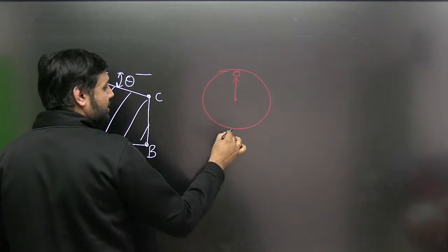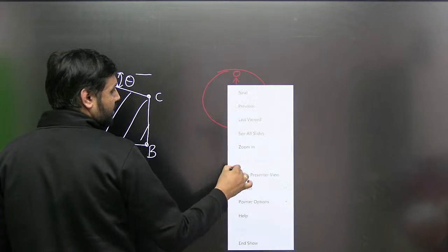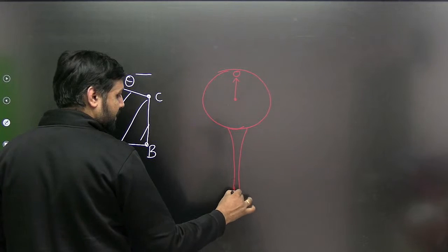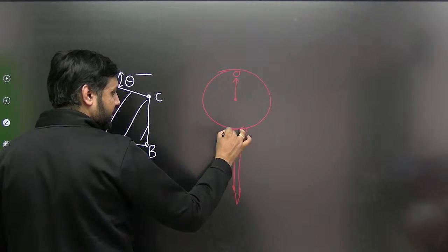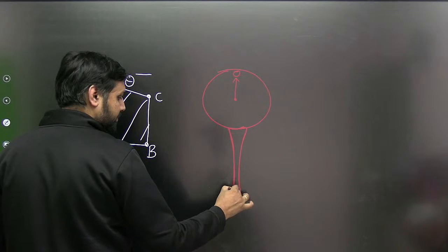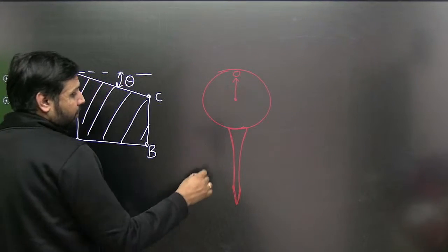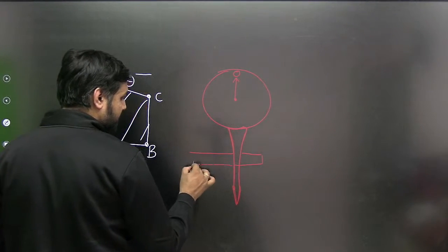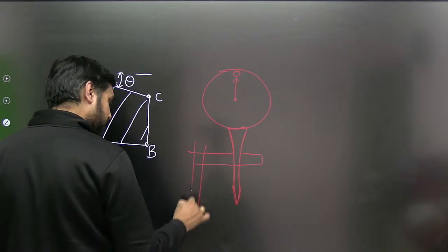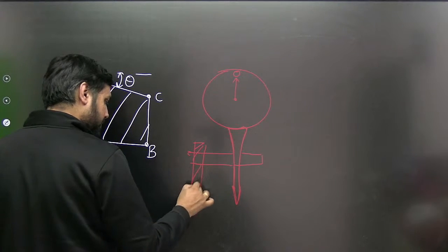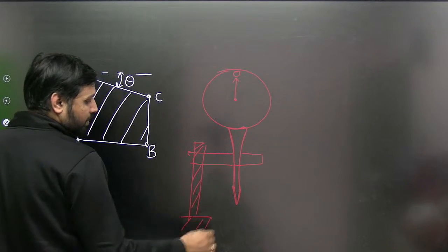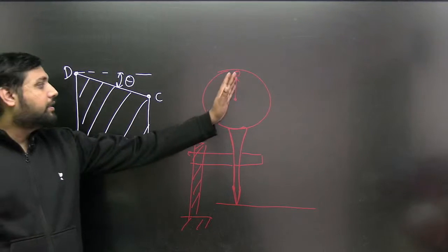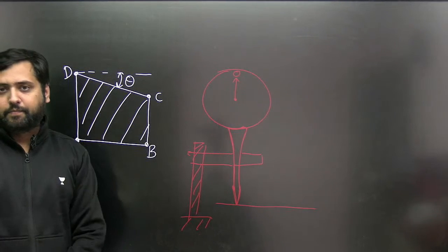If the needle is pointing 0, there will be a pointer here. If you move the dial gauge onto a plane, flat surface, there will be no movement in the needle.